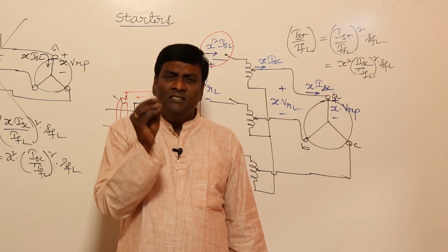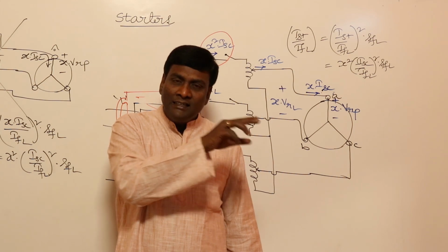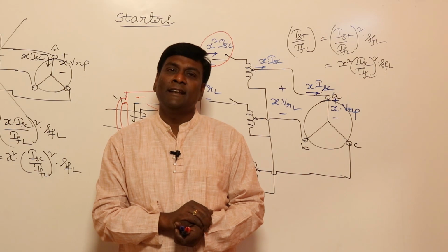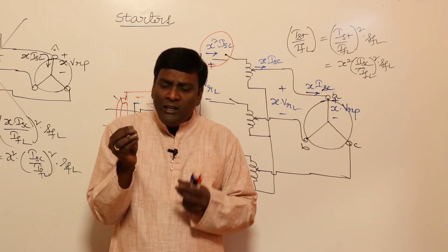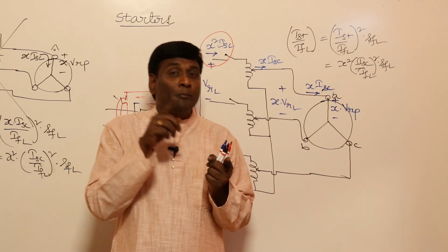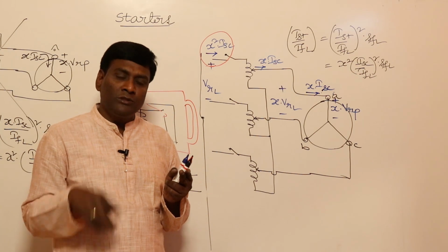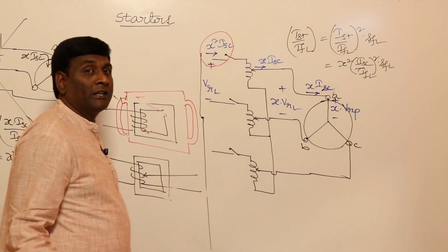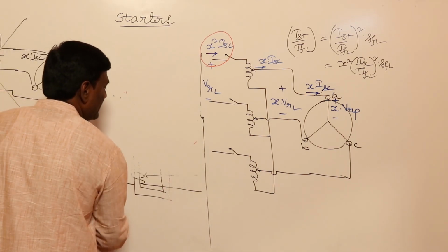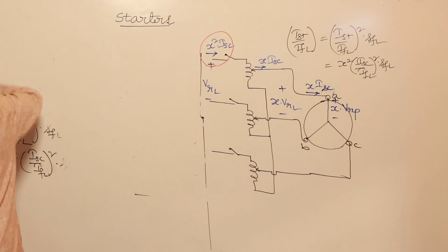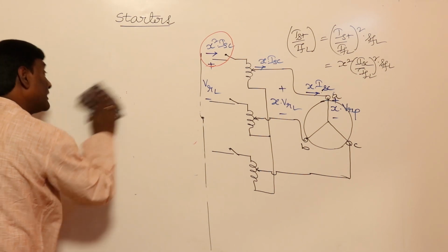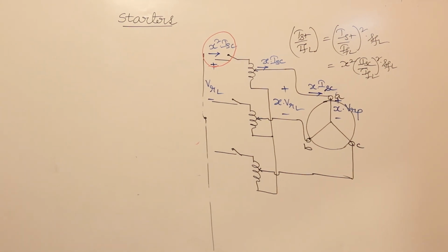So star delta starter, in the sense, is a switch only. There is no resistor inclusion or autotransformer inclusion in the system, only a connection change. So the combination of motor plus starter, that is switch, is going to be reduced. That's why most induction motors, at least medium level induction motors, will be connected in delta. Now let us think of star delta starter. For sure the machine should be designed to be connected in delta.